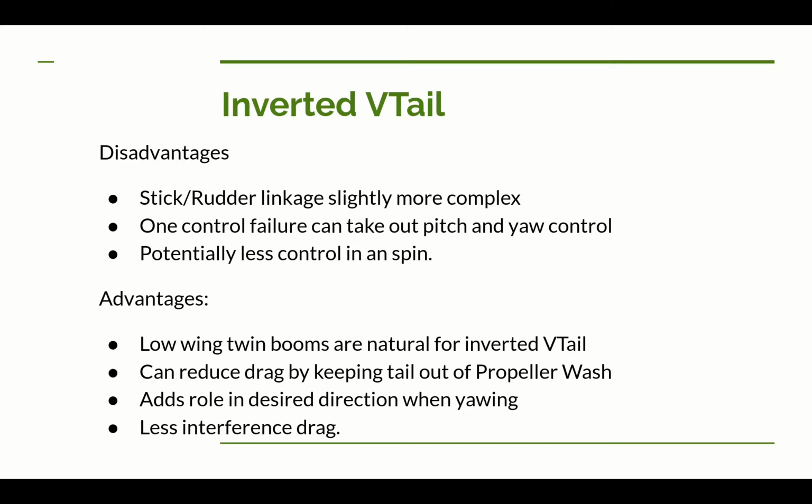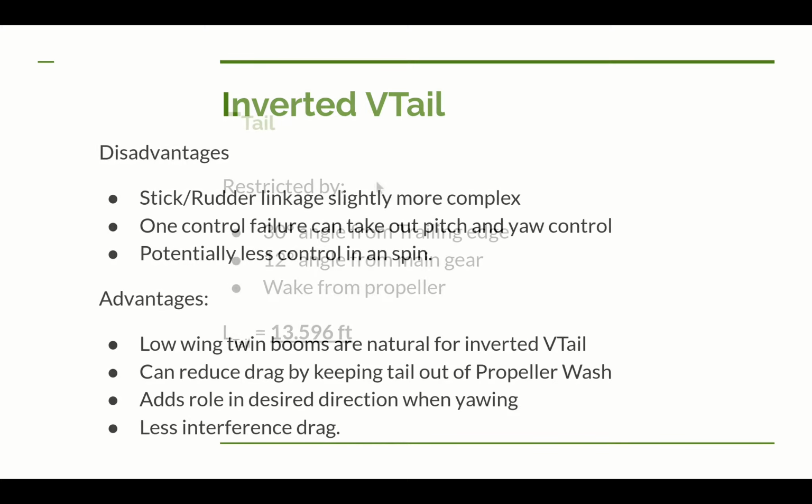So you can have the same thing on the tail. For example, in a place where a horizontal and vertical tail meet on the aft portion of that little junction, you'll frequently have interference drag if you can't find a good way to fair it.